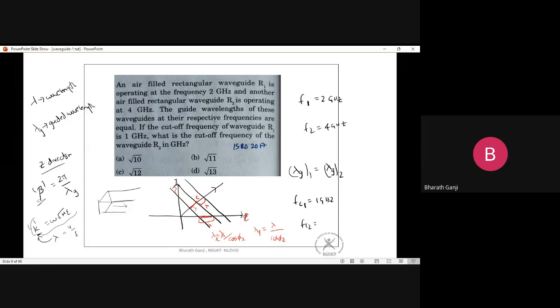I do not know in which direction the wave goes in the waveguide, but what I want to see is particularly how the wave travels in the z direction, and that answer is given by the propagation constant or phase constant beta. From that phase constant I get the wavelength in this waveguide, for a non-uniform plane wave traveling in the waveguide. So the guided wavelength expression is lambda g equal to 2 pi divided by beta. So this is your answer.